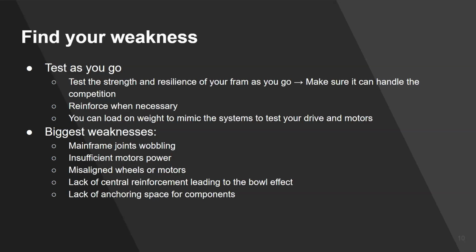Testing it beforehand, I used to tape down my motors before I would drill them into place so that I didn't have to remove the integrity of my frame, but I could see exactly where I needed them. So I taped them really hard into place. And then the moment you're done, even before you remove the tape, drill them into place and then take the tape off. That way you know that they're going to be properly aligned.